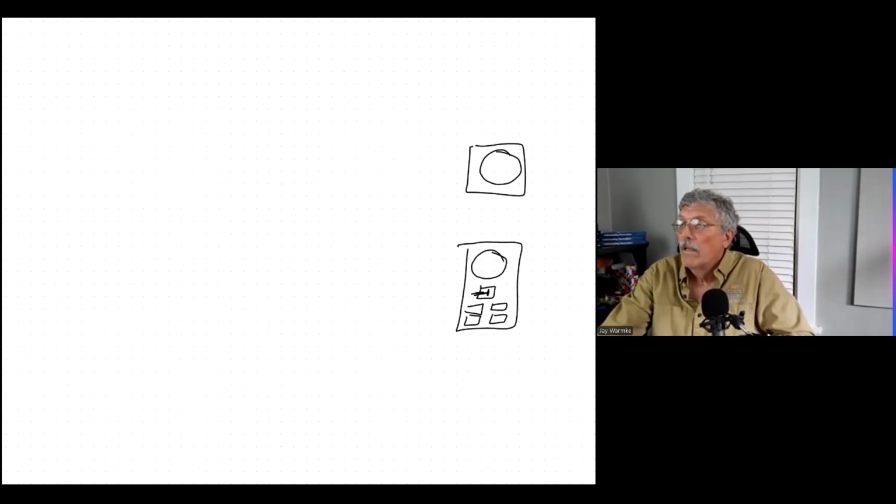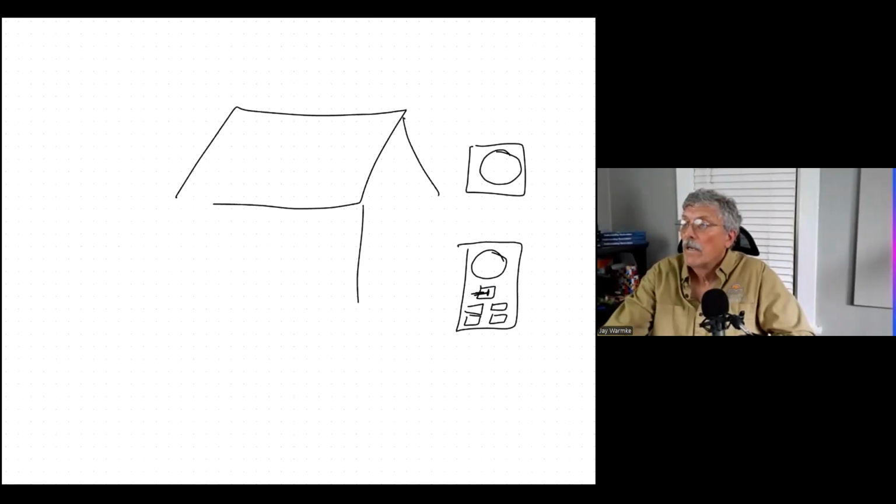Well, now if I want to hook my solar array in, let's say I've got microinverters, rather than going and drilling holes back and forth through my roof. Well, if I've got microinverters up here, they're already generating AC, so I don't need a DC disconnect.